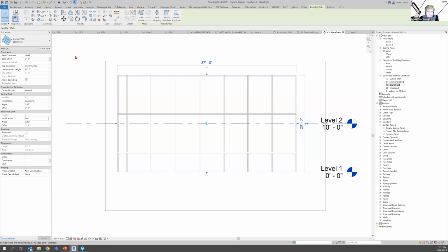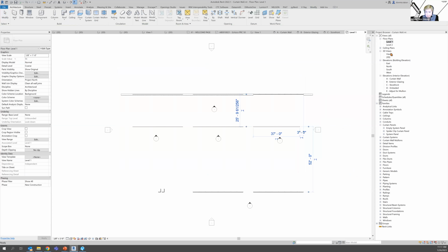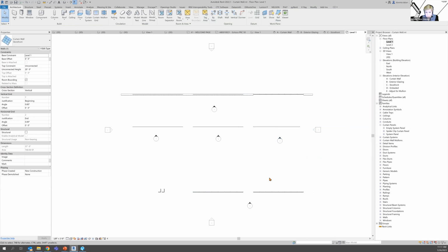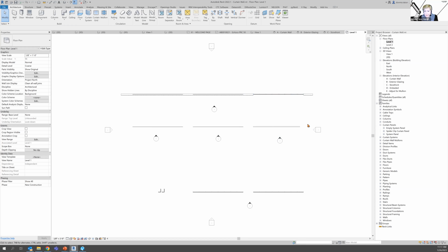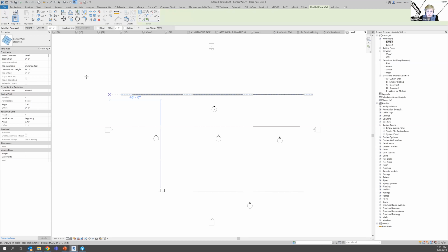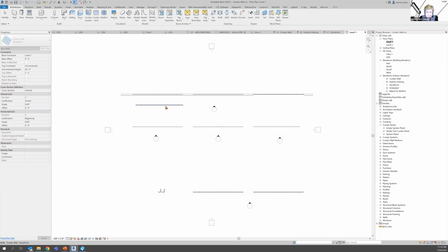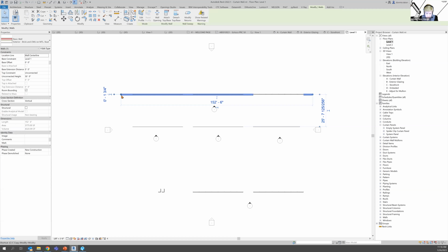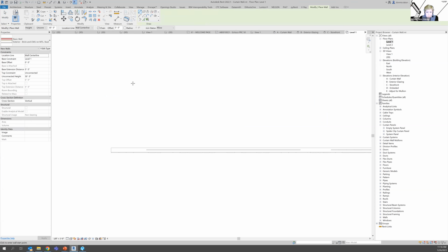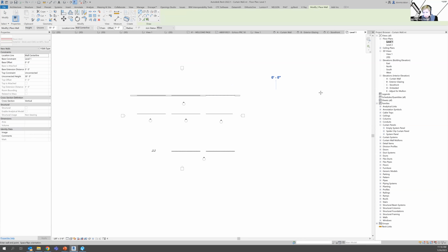So I'm going to go into my plan view here. Because I was doing my elevations from what we consider Project South here, I drew all of my walls from the right to the left. It's a rule of thumb with walls that if you want the outside of the wall to be to the outside, you can either go through and flip it, or you draw in a clockwise motion to keep the outside where you want it. Not as easy to see with this. Let me go get this wall. This one is the brick fascia. So I'm gonna do this over to the side, and I can draw around this way and like this and like this.